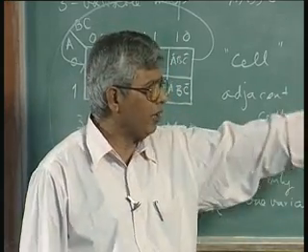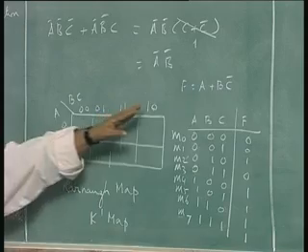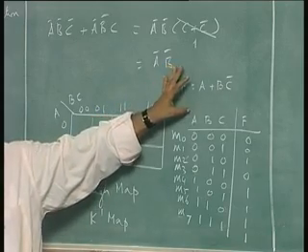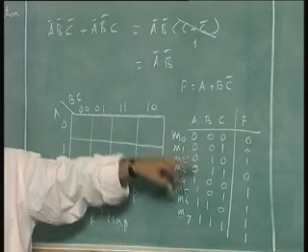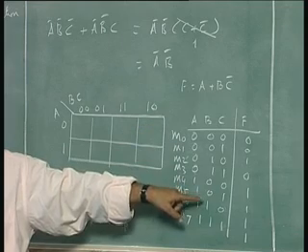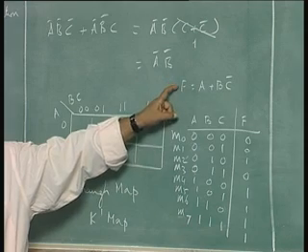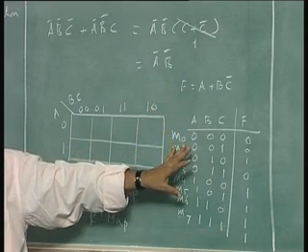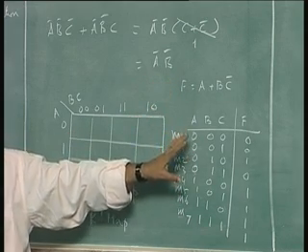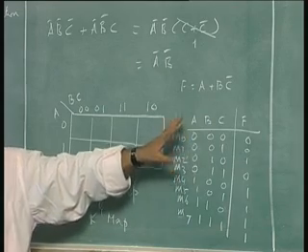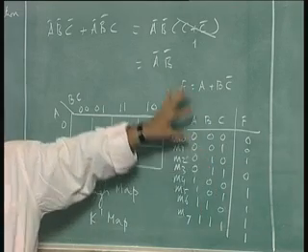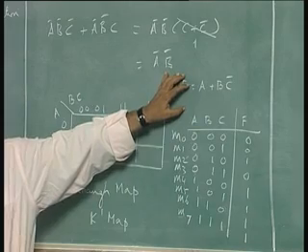So, I do not even have to write this truth table. Of course, this one is what we should get finally, this is what we started with. But this is the truth table which we considered and said that this is same as this. We first do a circuit for this, then we said the circuit represents a truth table of this type, and then we proved yesterday using Boolean algebra that this table can be represented by this function.